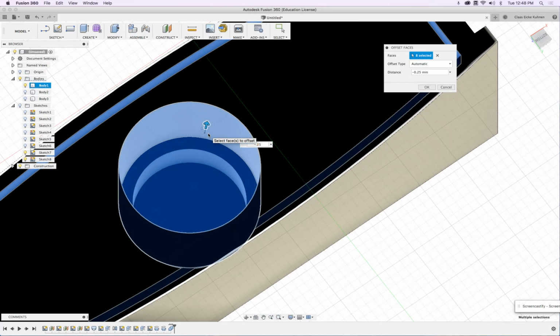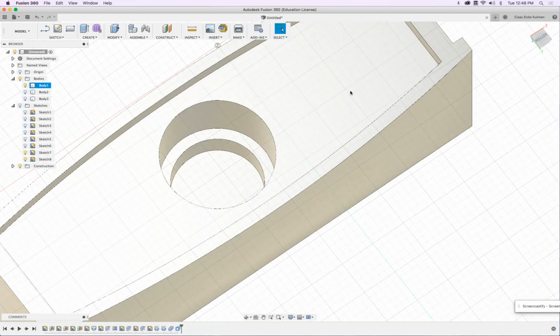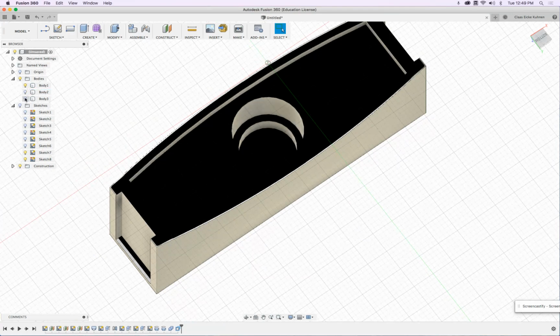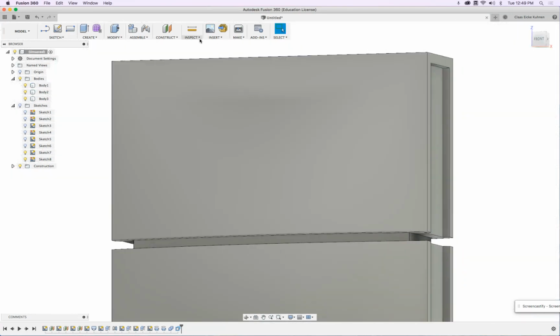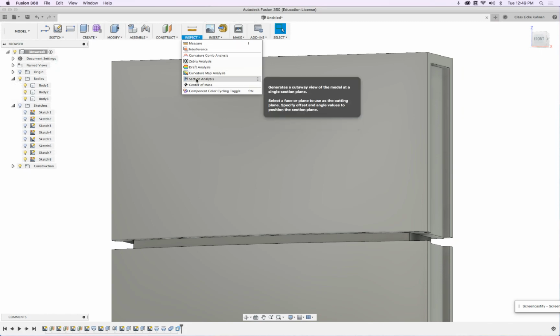It's basically each direction, which means we add 0.5 millimeter of a gap. That, for example, will help us when this is inserted, that the different parts don't touch each other.